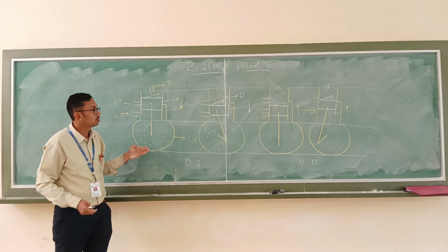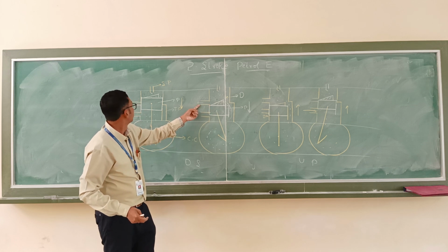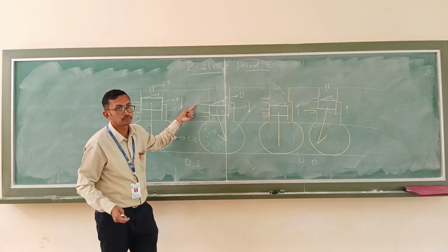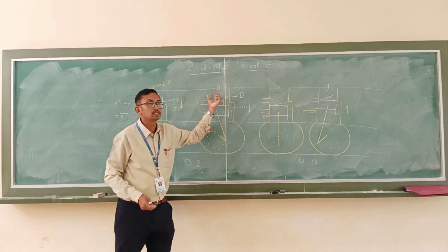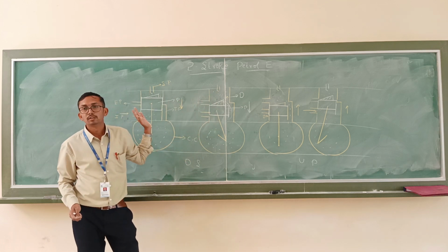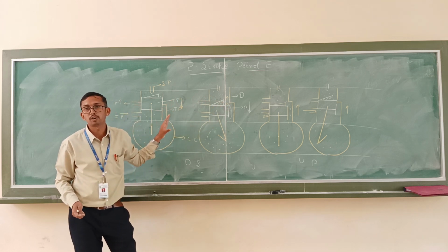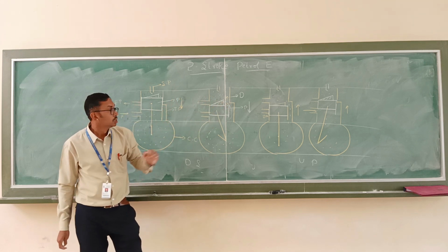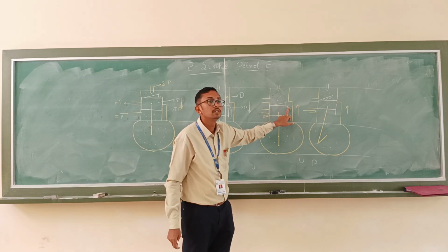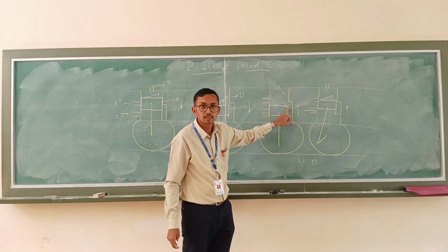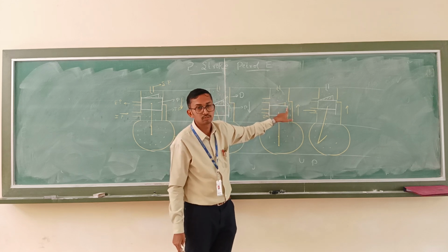So during the movement, what happens? First it is going to open the exhaust port. When the exhaust port is open, some of the hot gases are going to escape out to the atmosphere from the cylinder. With further movement, what happens? It is going to open the transfer port. Okay, so that is the starting of the upward stroke.